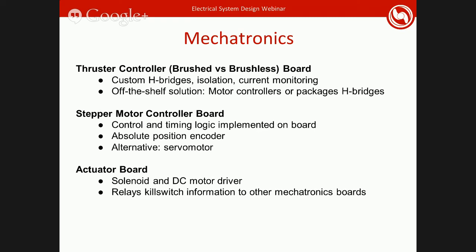So on this board, we will implement things such as H bridges, isolation, as I mentioned before, just to keep the rest of our electronics safe in case a thruster just stops working and sends a huge spike of current back onto our plane. And then current monitoring.